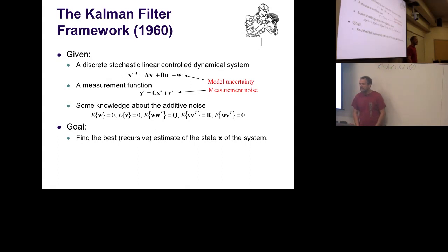It's really annoying. What people do, for instance, if you have a constant state, is create state equations which say y_{n+1} = y_n + w_n. So this is now a drifting system. Normally you would assume y_n and y_{n+1} are completely constant, but maybe it's changing over time for some reason. If you add a noise term here, it becomes a drifting system, which just wiggles slowly away. Very cheap way of modeling. It's not a good model, okay? It's a pretty poor model. It basically says, I have no clue what I'm doing, so I just add some arbitrary noise term.